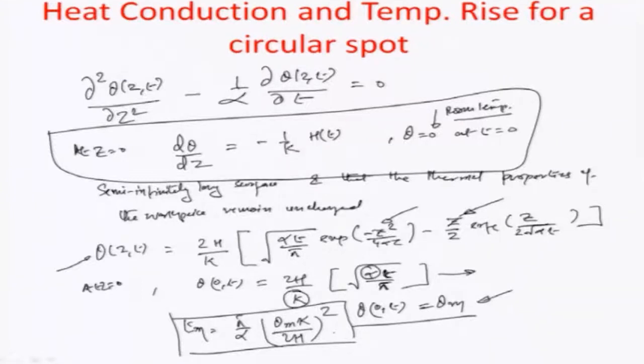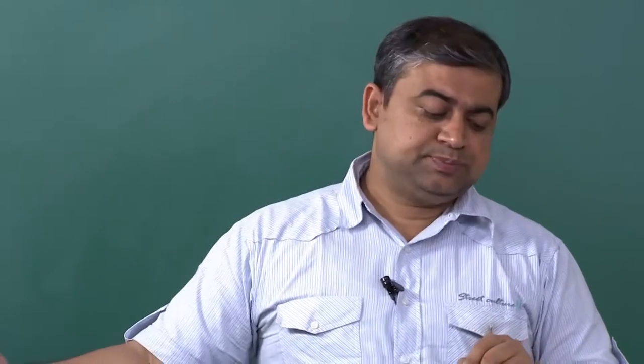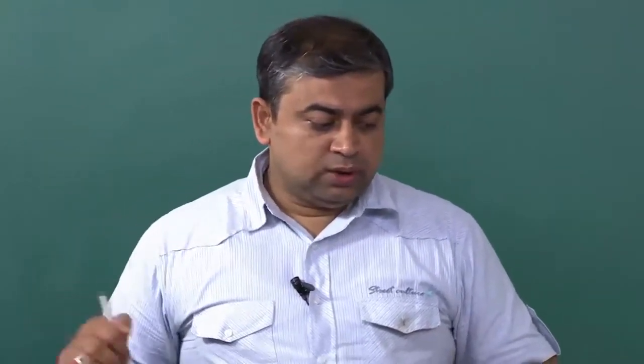We tried to calculate in some cases what typically this time would be, and we obtained for a normal system where we were trying to machine tungsten surface with only a 10% coupled power of the beam, a time of almost about close to 53 microseconds or 5.3 microseconds, which is actually a very small number in terms of time of machining. So, this process is really very fast in comparison to some of the other processes that have been illustrated before. So, let us now work on a slightly different